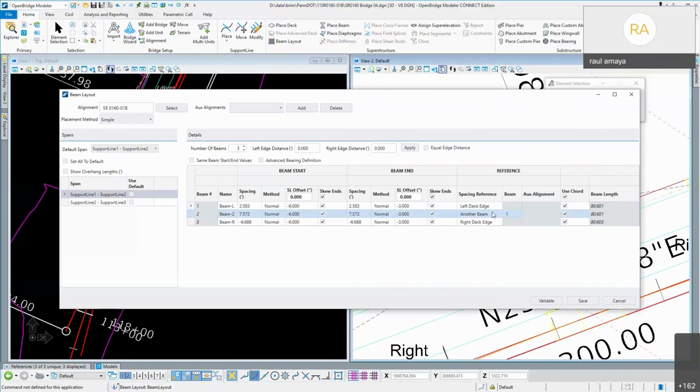In a situation where you want to go through LEAP, you mentioned, Alex, the 3 models. You might want to analyze, but the interior girder probably has more strength than the exterior. However, you make the exterior with the same capacity as the interior girders. Of course, you want to check for maybe construction loads, maybe. But